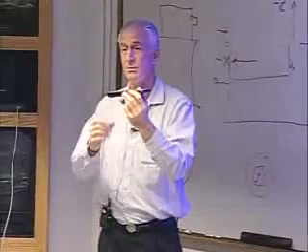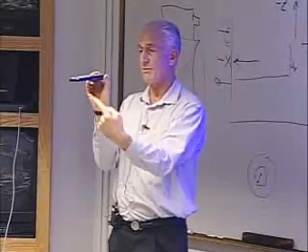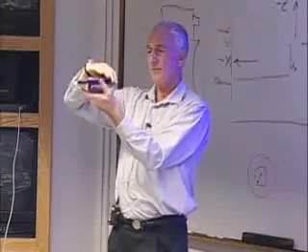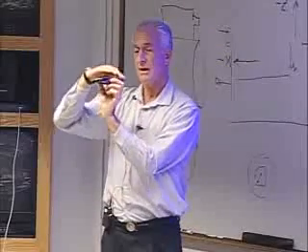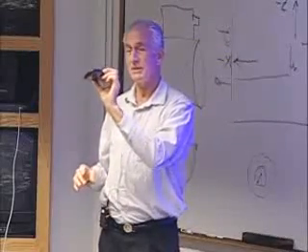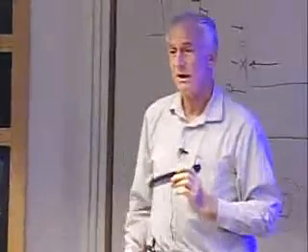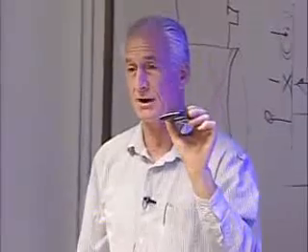If you want to do a roll, for instance, you'll fire the 45-degree down forward thruster and the downward pointing aft thruster, but they're not completely balanced. So you'll get a little bit of pitch and a little bit of yaw. You don't use the verniers for propulsion at all.